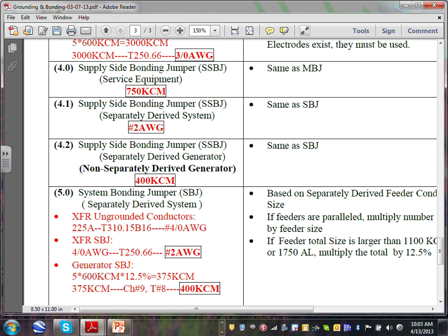Long story short, the wire disappears. But you have to have bonded both ends though. Typically for smaller ones like this, unless it's a big transformer coming from the bottom with a conduit, and if that's a bigger transformer coming from the bottom, then these will be PVC anyway, so you don't have to worry about these, right? And then you just pull a conductor inside the PVC to bond the two equipments together.